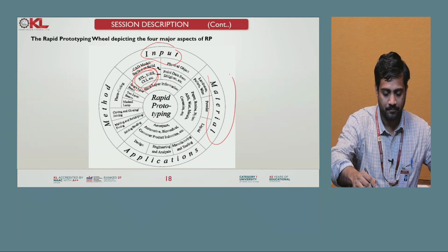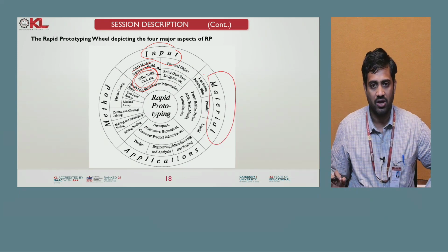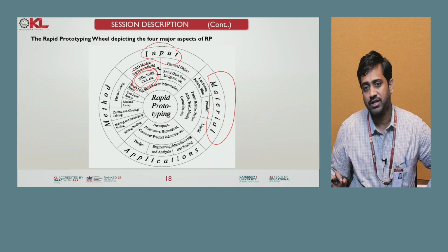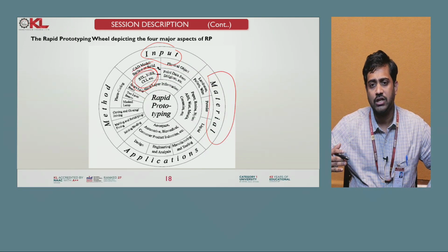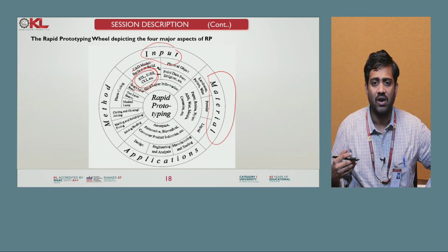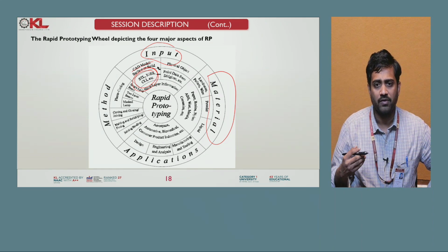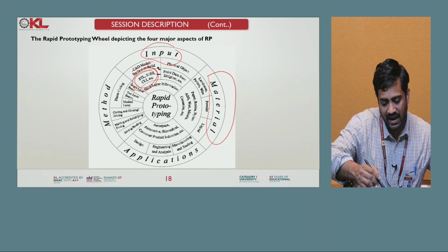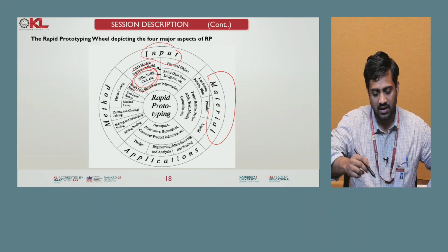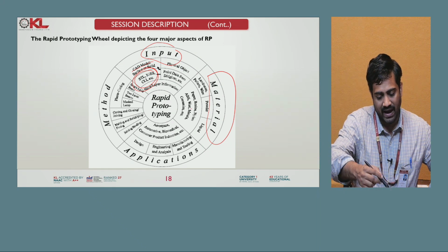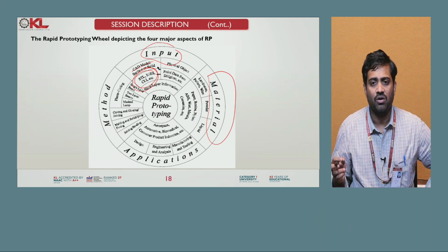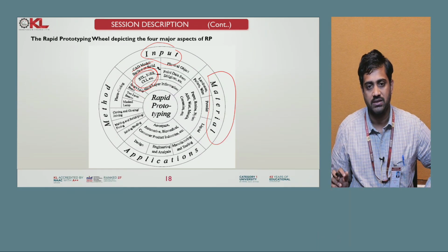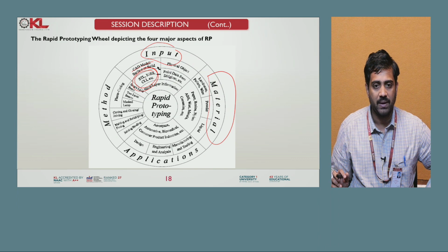Next, material. In rapid prototyping machines, we have liquid based machines, powder based machines, different machines are available. The raw material which you are giving to the RP machine, we can give in the form of a liquid, in the form of a powder, or in the form of laminates or wires also. Papers, resins, nylon, ABS, wax, metals, PLA, PETG, these are all various materials we can use, through which we can print various components with the help of a rapid prototyping machine.